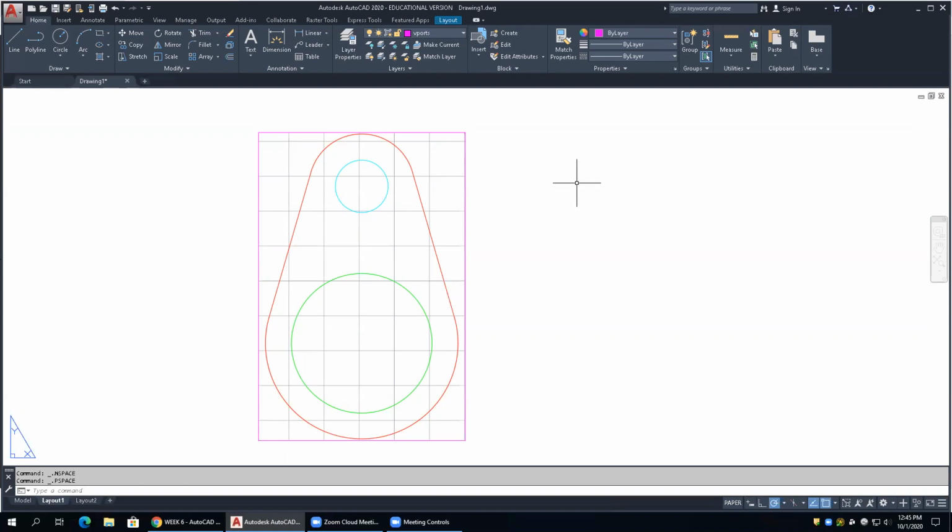So now what we're going to do is create another viewport. And so there's that top viewport, top right. We're going to use the coordinates there, 5.1, 4.1, 8.25, 7.45. So we're going to go into the mview command again, and we're going to just type in those coordinates. 5.1, 4.1.